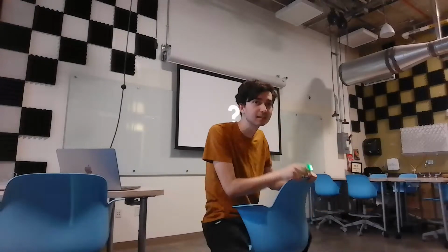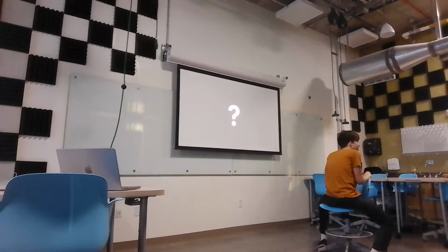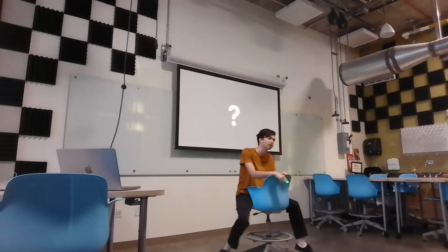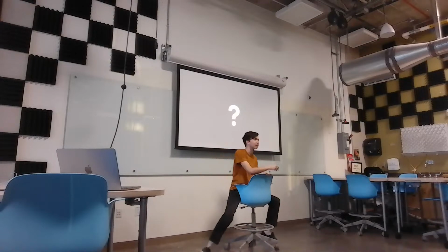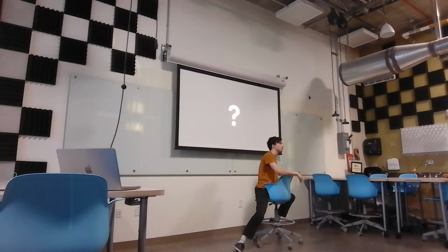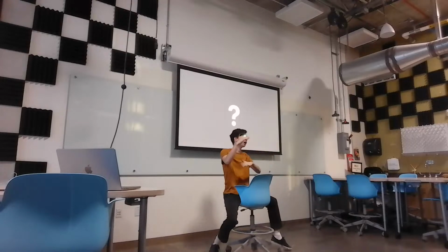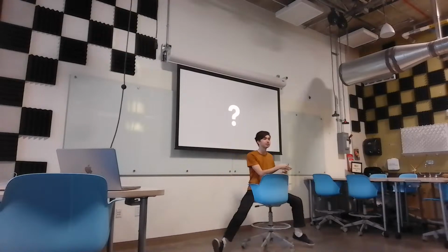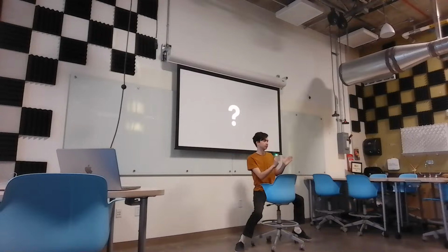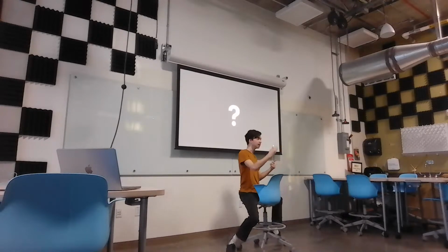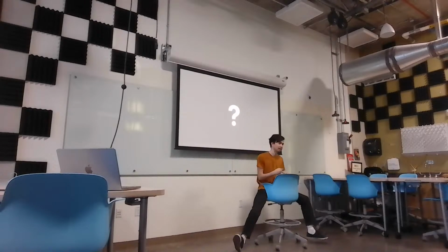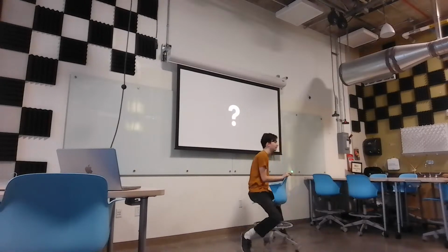You could use pulse width modulation to lower the effective voltage. Pulse width modulation. So let's see, what's Leo saying? He's saying, instead of having it on all the time, let's turn it on, turn it on, turn it on, super fast. And the proportion that it's on compared to the proportion that it's off is going to result in an average current between off and fully on. And that will appear to us as dimmer, and it will appear to the circuit as a lower average power loss. Here's the thing though.